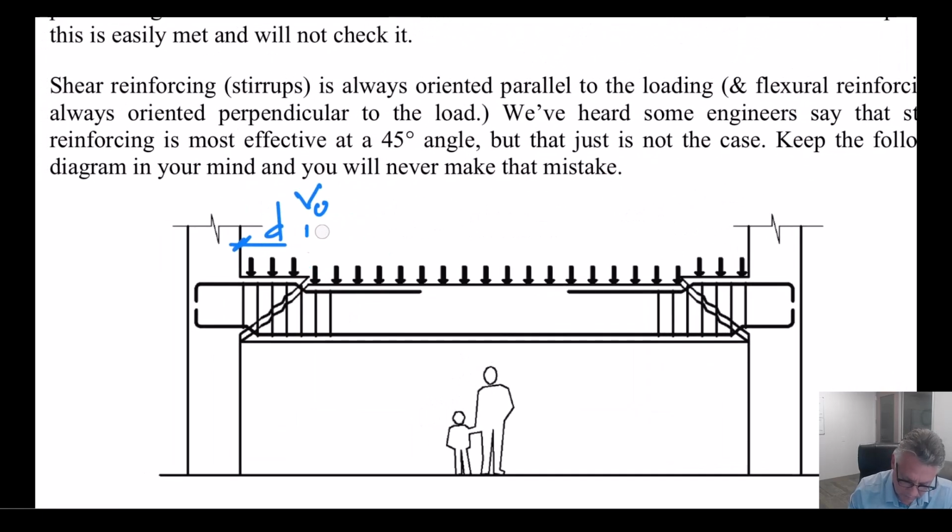Second thing is, we're not reinforced concrete, as they call it. We're post-tension concrete. We're pre-stressed concrete. Because D, remember D could be doing this, and D's doing all kinds of stuff, and D is never the same in 2 locations, theoretically. So we don't use D in pre-stressed concrete. What the code uses is H, and instead of giving us the full H, they've decided that our demand is taken at H over 2. So in your project that you're going to work on, that's where your first check will be. That's where your demand capacity check will be done. H over 2. Okay, we don't use D.